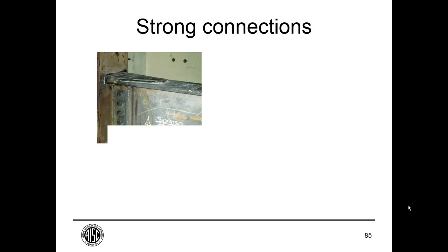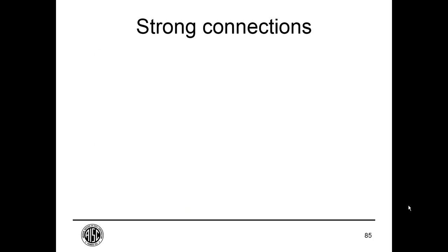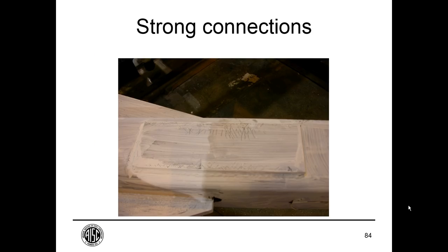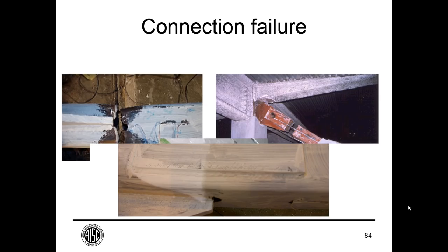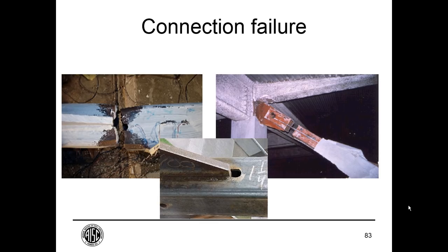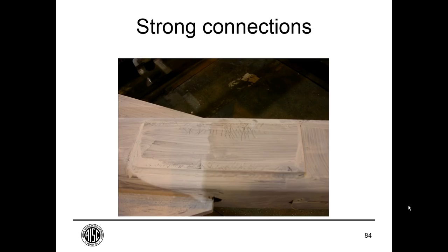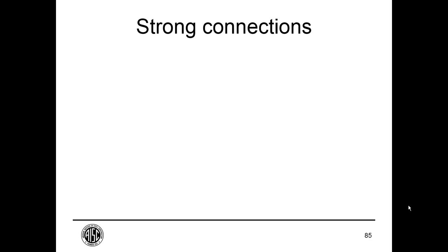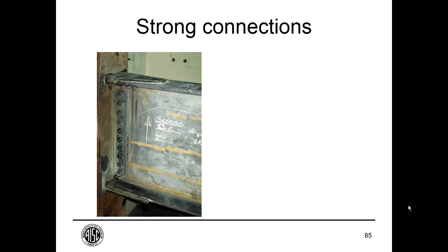For braced frame connections, so that's a braced to gusset connection, slotted, and in the previous slides you see where that has often, on the left in the laboratory, on the right in an earthquake, often failed. It's been a weak point in that brace connection. And so here in this test, similar brace connection but with a reinforcing plate, and that drove the ductility into the bracing member.